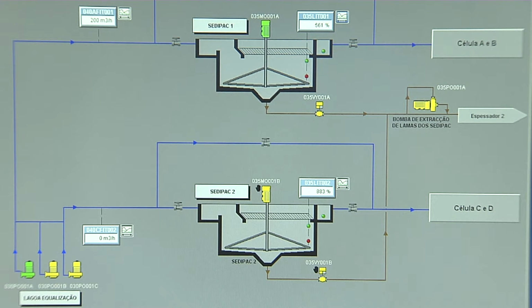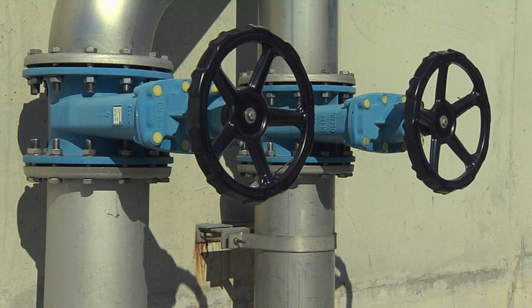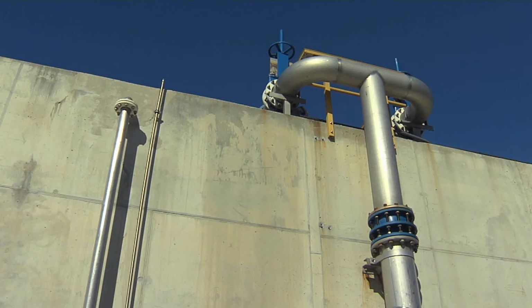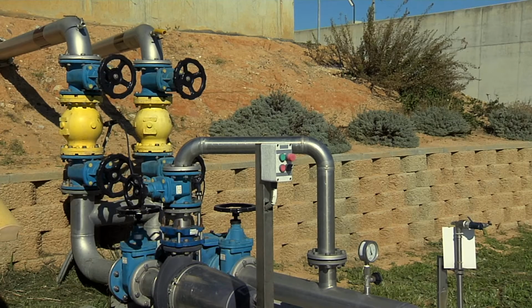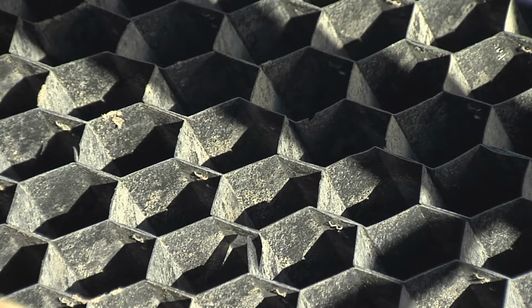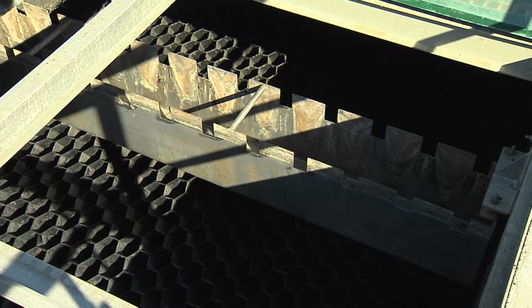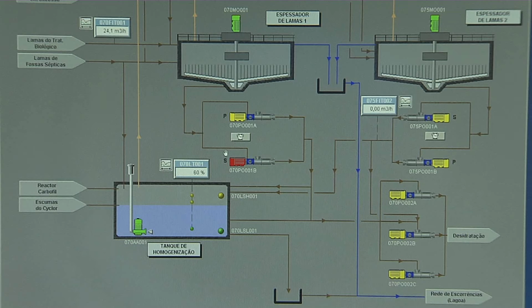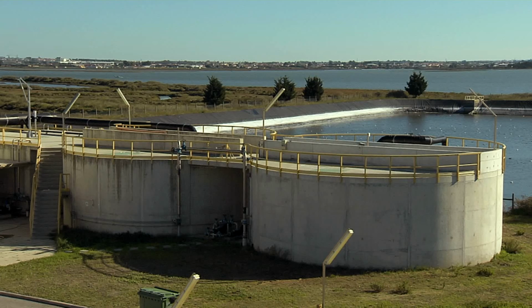Secondary treatment. In secondary treatment, wastewater flows through sequential biological reactors and is cleared by the action of microorganisms in biologically controlled conditions. In these reactors phase separation also occurs by decantation, resulting in treated wastewater.